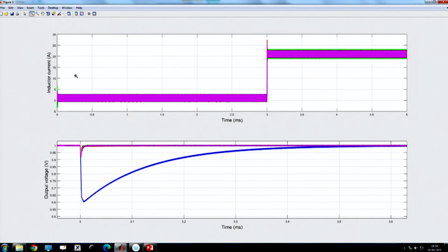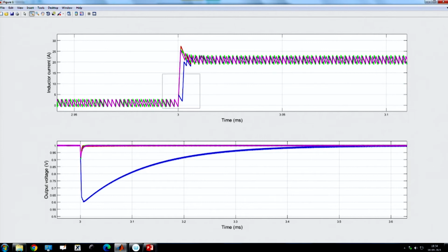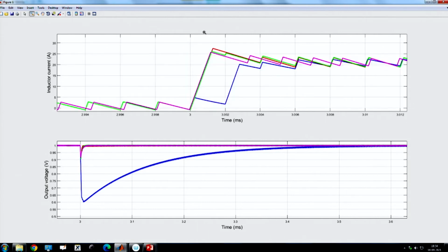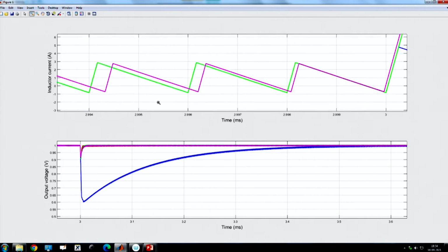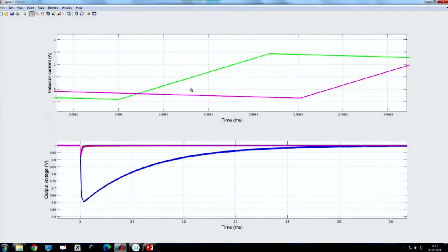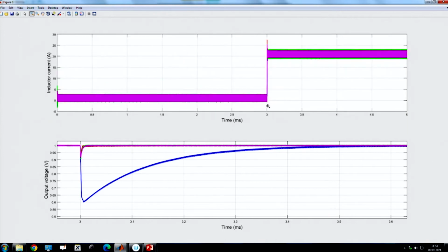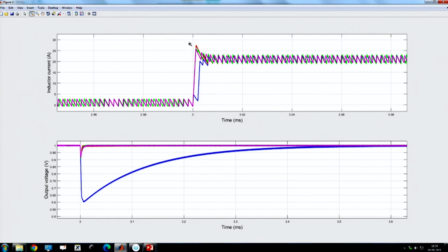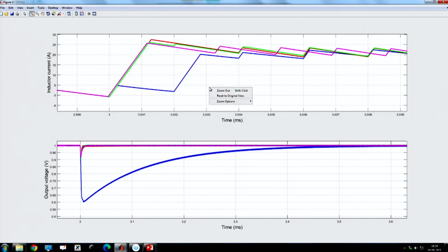Now, we can play with the switching surface, and you see there is a variation in the switching frequency in voltage based control, because if we do not choose the right amount of threshold or hysteresis band, then it may lead to variable frequency, and that is clear from the magenta color. You see it is not exactly common, whereas the large signal tuning and the regular control overlap at steady state. But you know this variable frequency is there in sliding mode control.